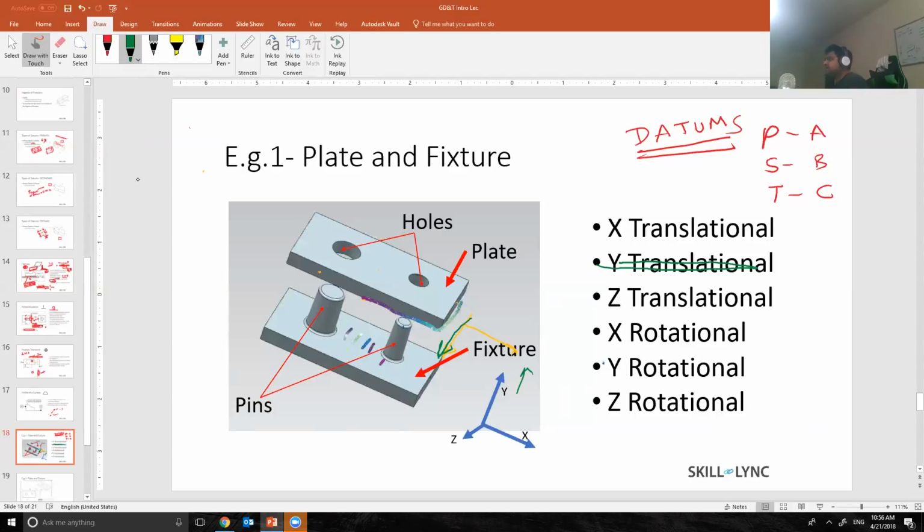Okay, my aim is to make sure that 3 degrees of freedom are constrained. So I know, okay, 1 is definitely constrained. Now let's talk about rotation. Imagine you're holding the book from the bottom side. Can it rotate along X? Can it rotate like this? If you're holding the book over here, can it rotate along X? No, because it's nicely and firmly sitting on the palm. So I've stopped X rotation.